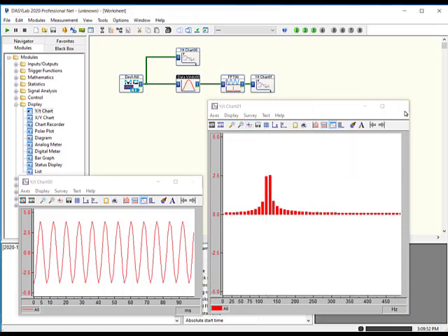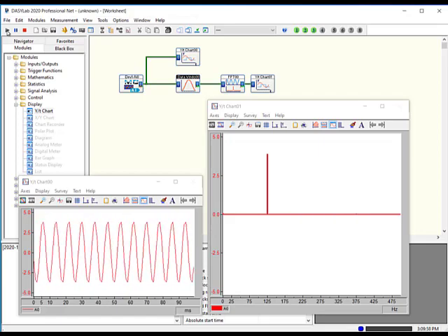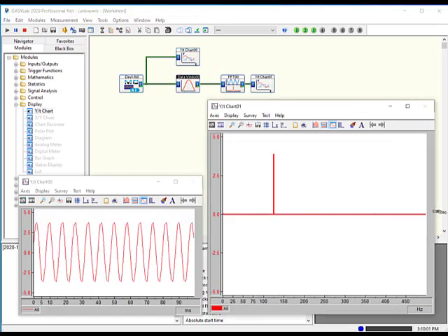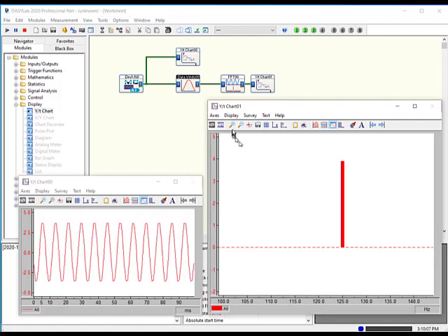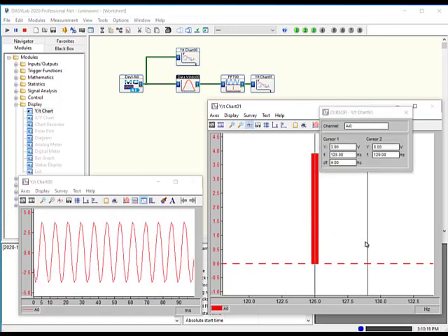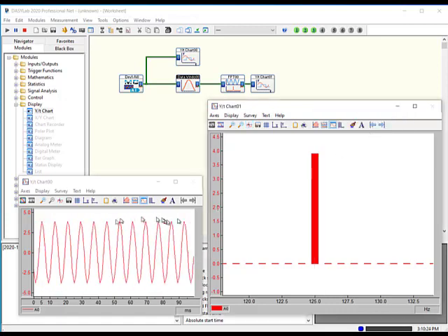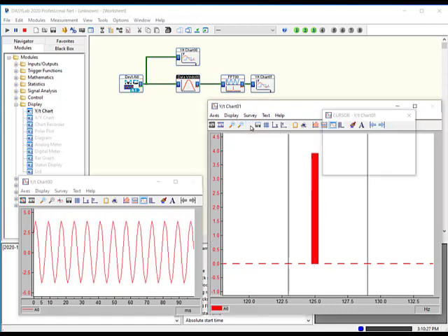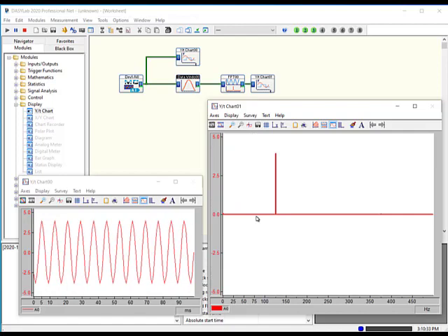I'll close the cursor window, I'll click Start, and a second later I have got the data and it's just much tighter to see. If I zoom in on just the peak, you'll see that I have a single peak right at 125 instead of being split over 2 frequencies. I'm actually impressed with my signal generator that it's giving me 125 Hertz. It's a clean signal. It's a very clean sine wave. You don't see any harmonics. You don't see any additional data in there. Unzoom it. So you see just the frequency.